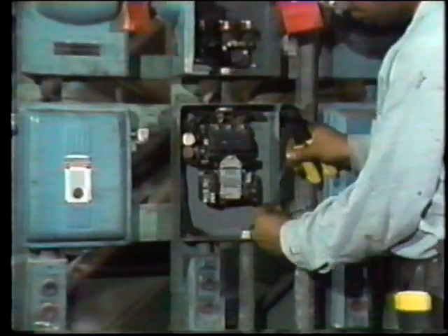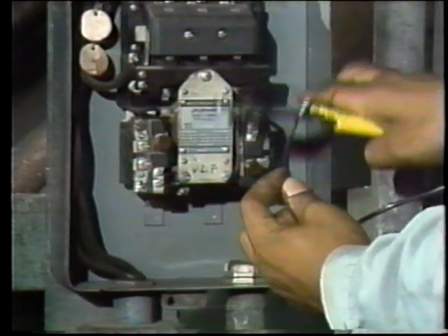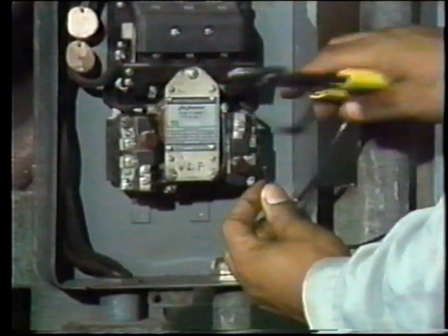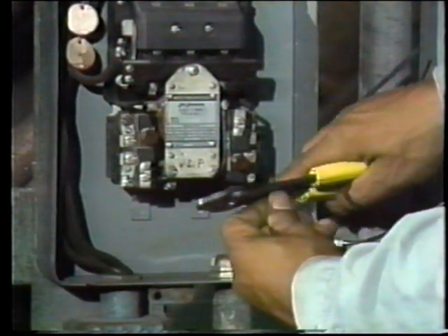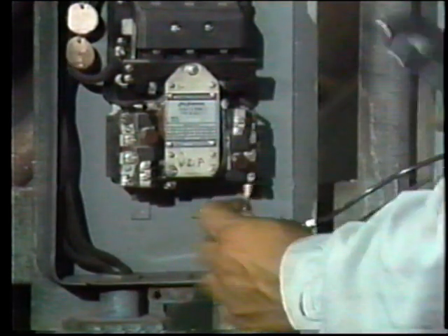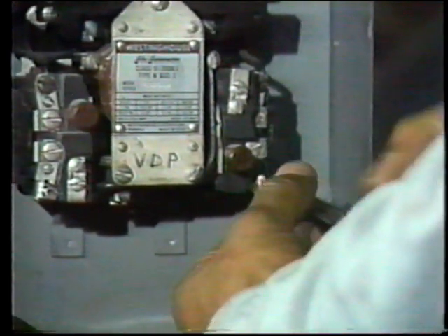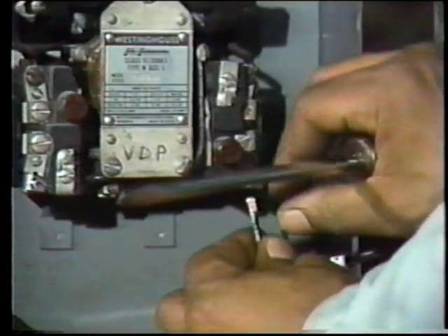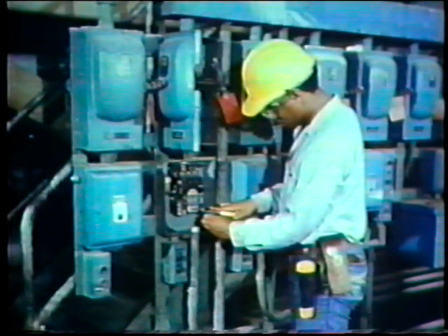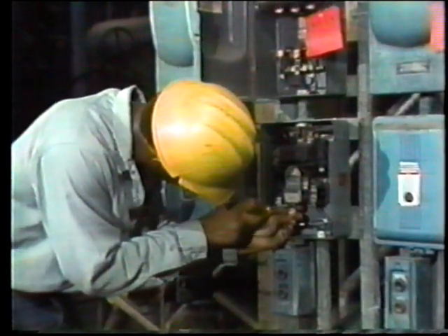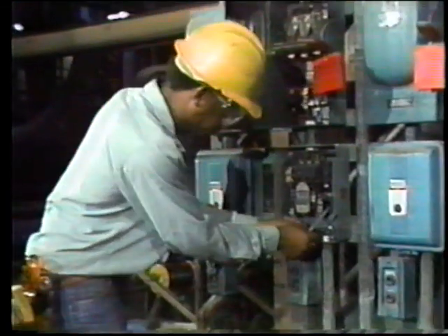Here, Bill's working with a set screw terminator. He measures the length of conductor he'll need to reach the set screw and snips off the rest. As before, he'll allow a little extra, in case he needs to go back to work on the circuit for another reason. Then he determines how much insulation he needs to strip and strips the insulation off. All he has to do now is insert the conductor into the slot and tighten down the screw to hold the conductor in place. Bill doesn't have to use tape to rebuild the insulation in this situation. Air serves as the insulator here due to the amount of space between the set screw terminators. Air is a good insulator.